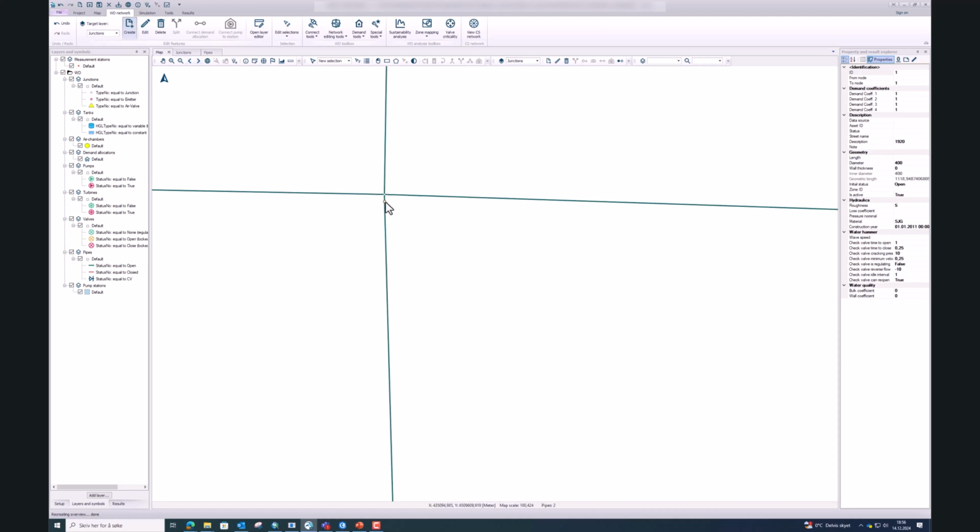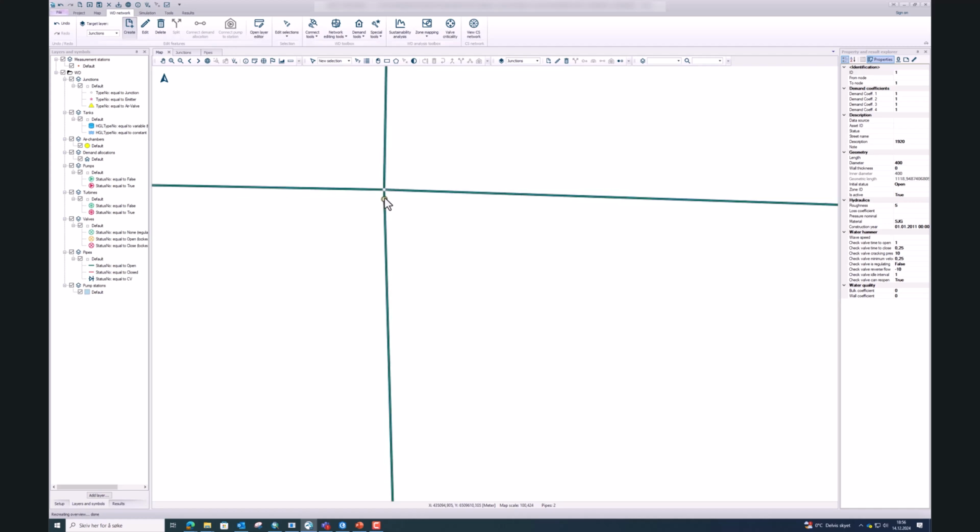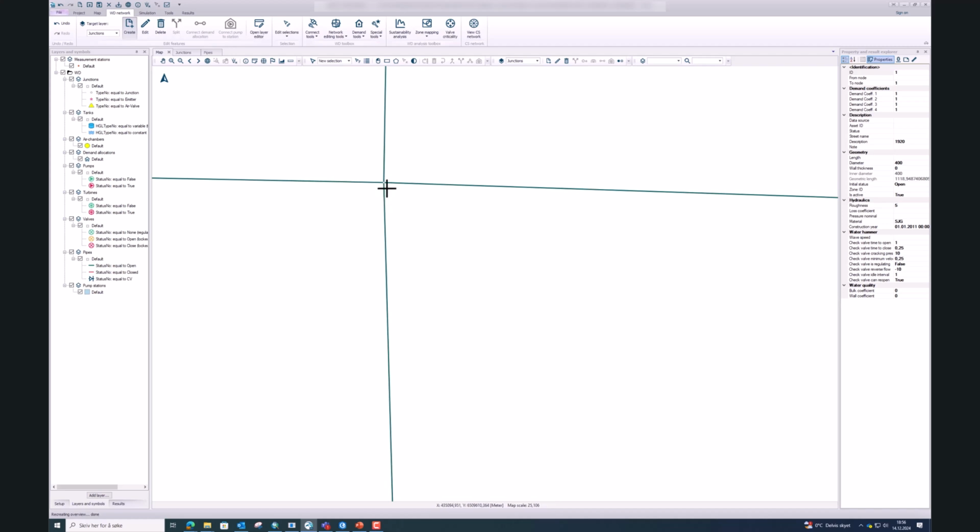So I'm just going to create one more junction. You should be careful with how you place it in case it becomes too long, but I'm just going to do it roughly here. And I'm going to say yes to split the pipes. And when I've done this, I've, as I said, split the pipes. We have 2 pipe segments, but I want to delete this small pipe segment, because I want my valve to go between these junctions. So this is how we model it in water distribution systems.